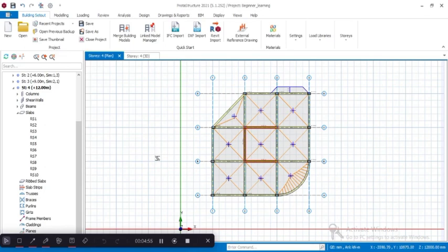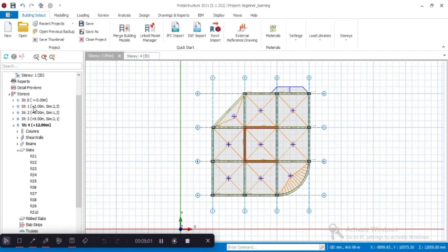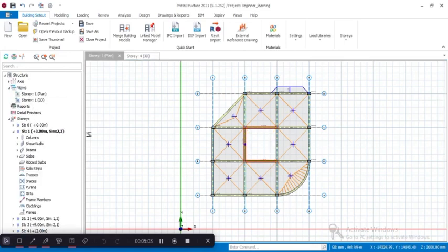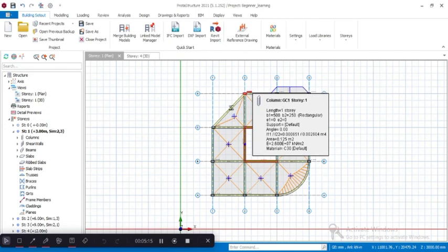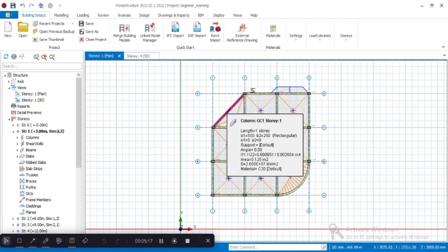Then when I insert brick wall loads on the beam in story 1, let's go to make story 1 active. So now enter a perimeter beam. Select the perimeter beam and click edit for loads. Let me use this beam now.